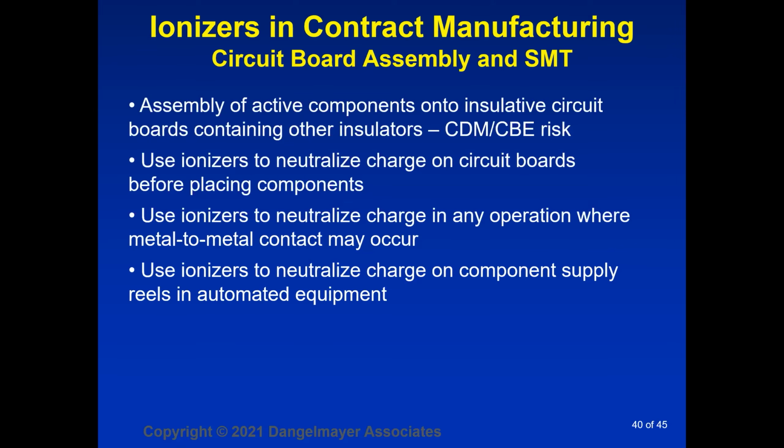Suppliers of ESD-sensitive components are almost always really good at packaging their products in good ESD-safe materials. However, there are other components that are not considered to be ESD-sensitive, resistors, capacitors, lots of other things. And very often the reels that they come on are insulators. So you have a very large charged object in that supply area of your pick and place machine. So we sometimes use ionizers to make sure there's no charge on any of the component reels in the feed area of the automated equipment.